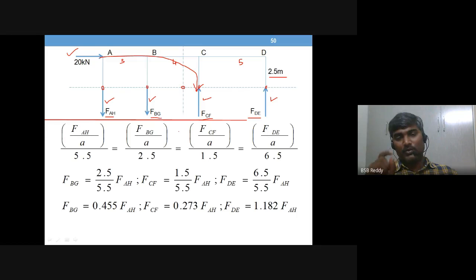Right. So how you represent the axial load is by looking at the applied moment, by the applied load. The applied load is towards the right, so that is going to turn the frame clockwise. So you should have an anti-clockwise moment. For that, what you need: to the left of the CG line, downward arrows.